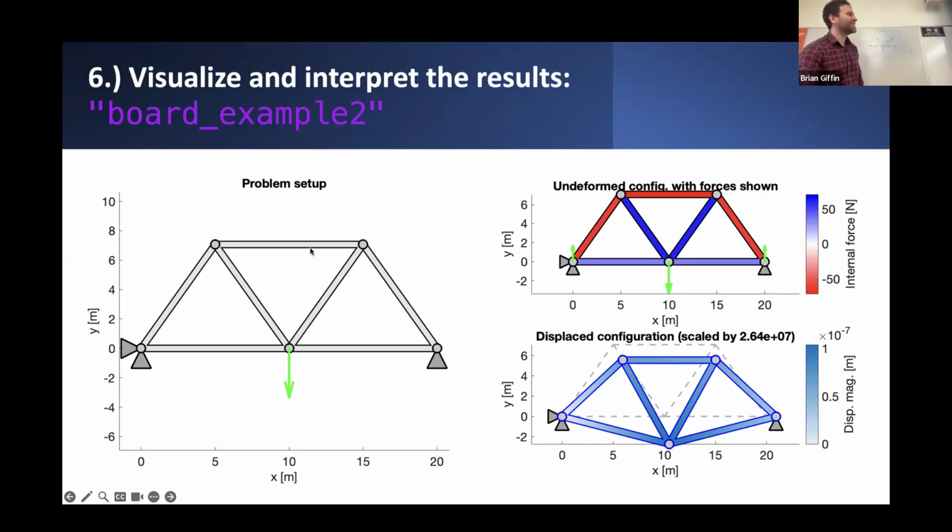Another way I like to visualize this is if I have a force hanging down on these two members, then I would think that's going to pull them or elongate them. So hence, I would think tension. That's probably the quick and dirty way to estimate that.